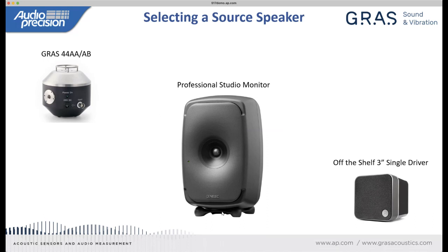The downside of a mouse simulator is that it is not actually meant to be a great speaker. It's meant to simulate the acoustic properties of a human speaker, and that has influence on the output level it can achieve, the bandwidth over which it can operate, its frequency response, and a lot of other properties.